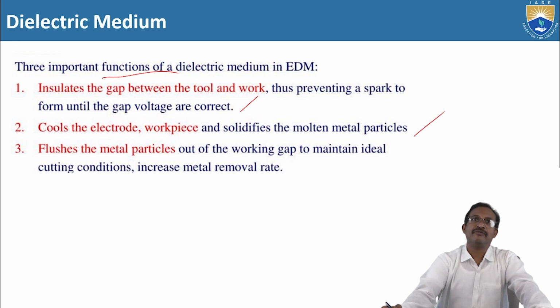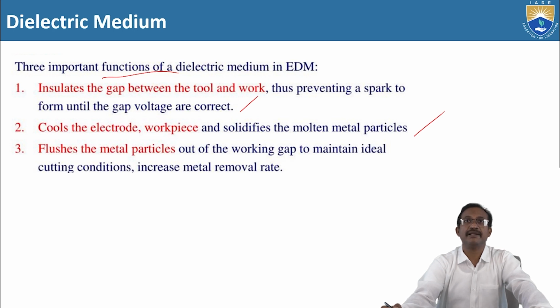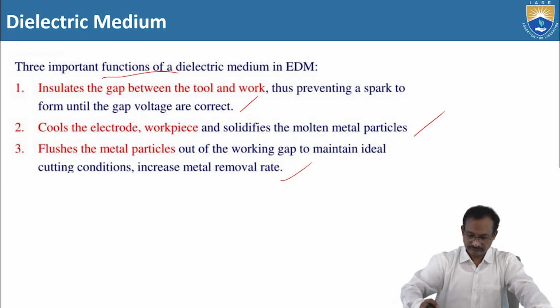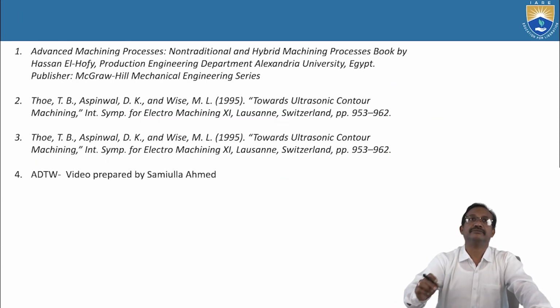Third, it flushes the metal particles out of the working gap to maintain ideal cutting conditions and increase metal removal. These three are the functions of the dielectric fluid medium.